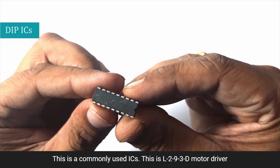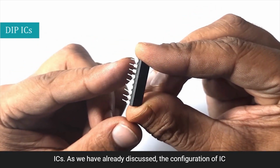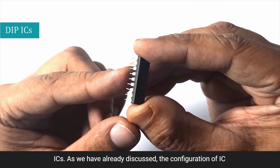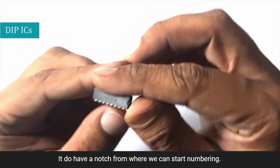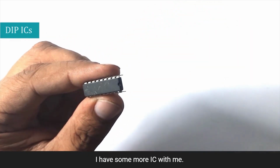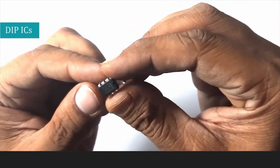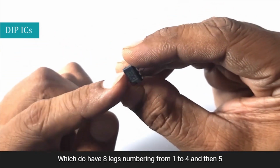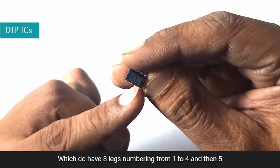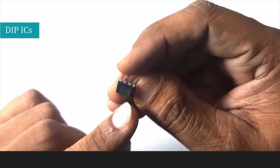This is a commonly used IC. This is the L293D motor driver IC. As we have already discussed the configuration of an IC, this IC has a notch from where we can start the numbering. I have some more ICs with me. This is an 8-pin DIP IC which has 8 legs, numbering from 1 to 4 and then 5 to 8, starting the counting from the notch.